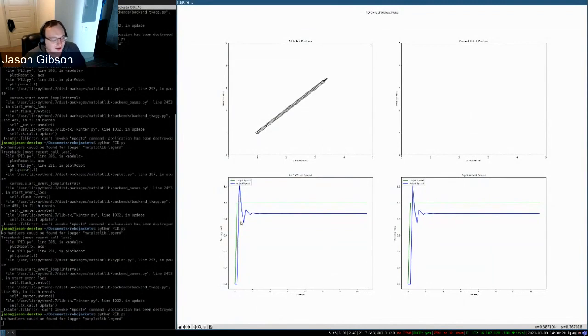I'm just arbitrarily playing with values here. There's always ways to tune your PID controller better. If you're spending an obscene amount of time tuning your PID controller, it's probably an issue somewhere else. How this tends to work is, if you get decent values, you'll get like 90% of the performance, but the last 10% is almost not worth tuning for half the time.